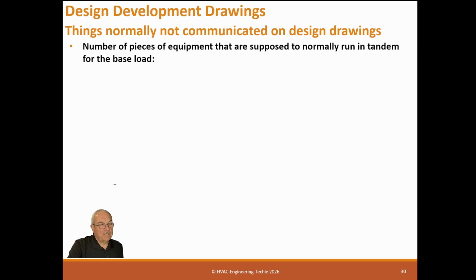And the other way we have to do it is to add up all the air handling units and figure out what their load is, and look at the central plant load and say, well, it looks to me like... now, unfortunately, diversity messes that up. So the contractor or operators can never know what the diversity really is, because only you as a designer, who has actually seen the load calculations, the difference between the zone load and the block load, know exactly what the diversity is. So everyone else is guessing. So you need to make sure it's clear on the drawing.